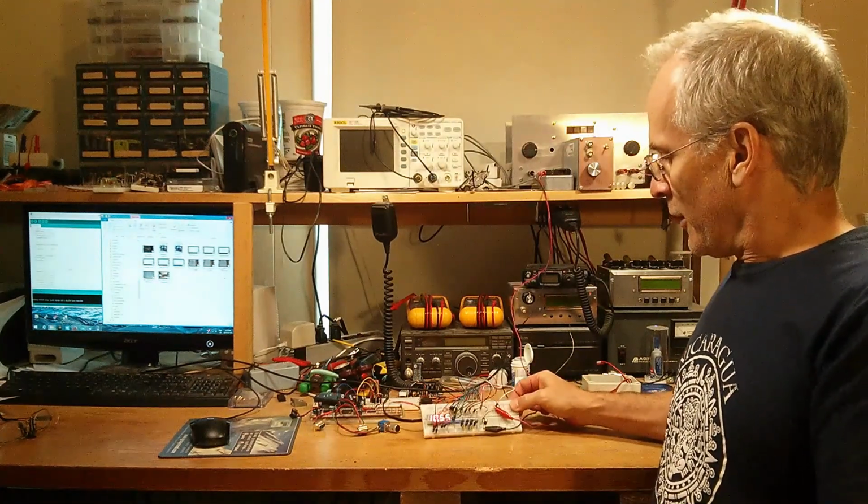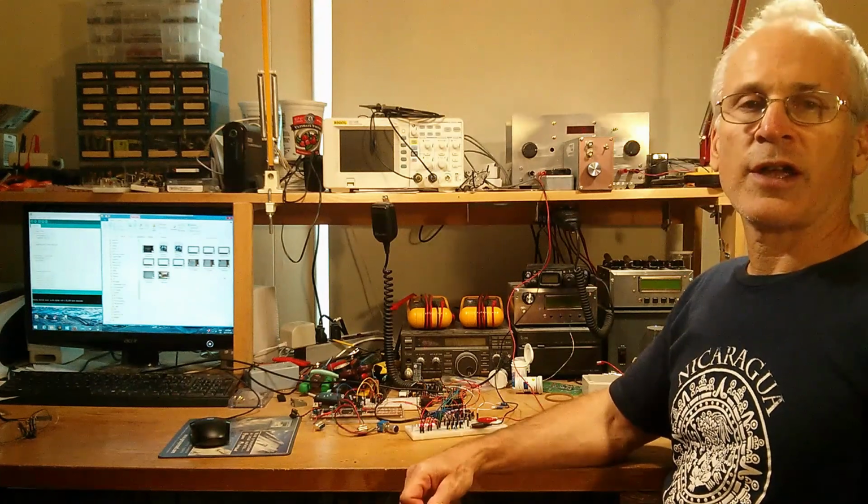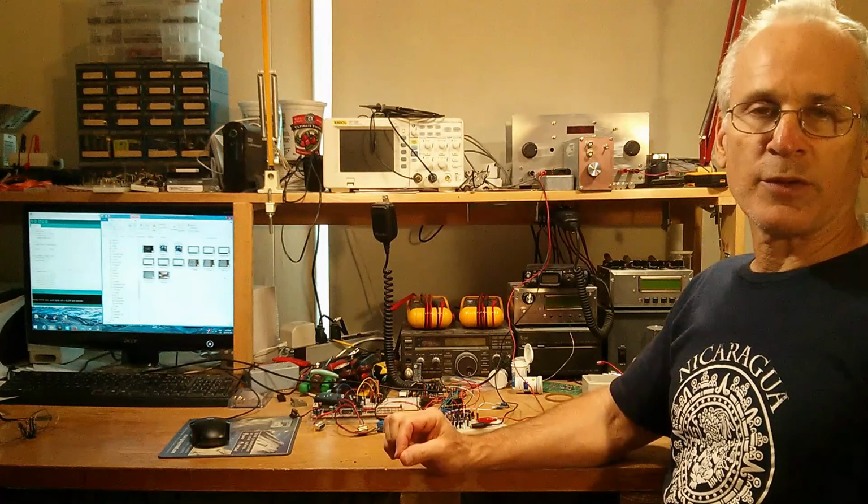Well, there you have it. A simple digital voltmeter. If you've been following along this series of tutorials, I presented a lot of information about interfacing to a microcontroller using the Arduino as the example. So we talked about how a digital I/O pin actually works. We talked about the limitations of loading it and drawing more current out of it. We learned how to connect an LED to it with a series current limiting resistor, and how to calculate the value of that resistor. We learned how to use a transistor to drive more current than what the I/O pin can actually handle, and how to do the calculations for figuring out the base resistor and other simple characteristics of the transistor. And we learned about multiplexing, using the same I/O pins to do different things.